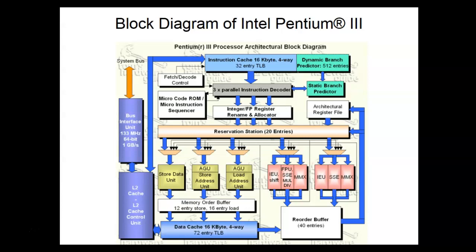So here's the actual microprocessor right here. And this is a heat sink. The problem they try to do is make the components themselves really small, which means they don't have enough surface area to get rid of the heat. And so you calculate thermal resistance almost exactly like you do Ohm's law. Every device, every metal, has different thermal resistance.